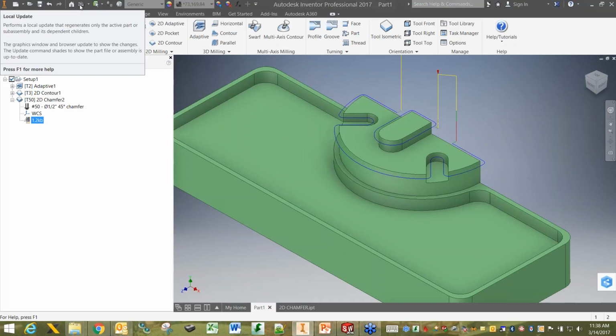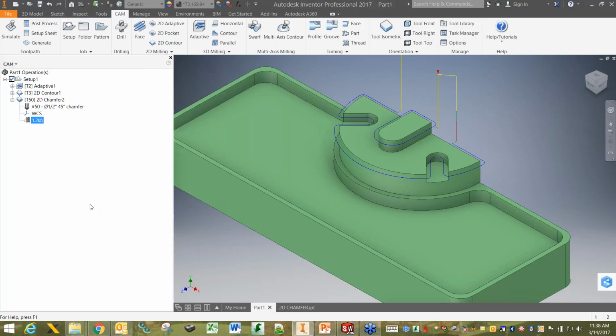So it's not just manufacturing. We see it in assemblies. You know, you're putting together an assembly, but you buy this part and you buy this part, or you're putting together an assembly and you have a contractor that builds this part in Pro Engineer. When you bring those into the assembly using the AnyCAD, you just keep them linked, and if those parts change, all you have to do is hit the update button from within Inventor, and it'll update to the new model geometry.